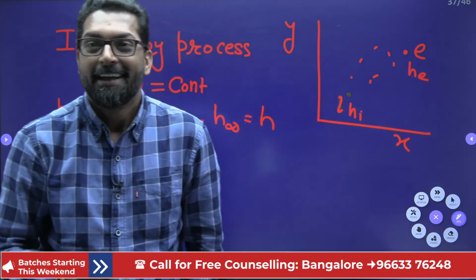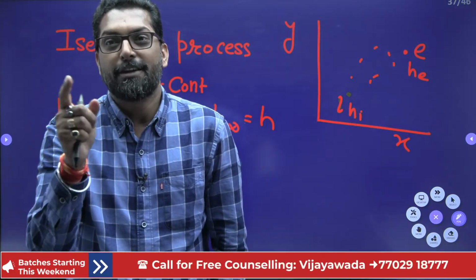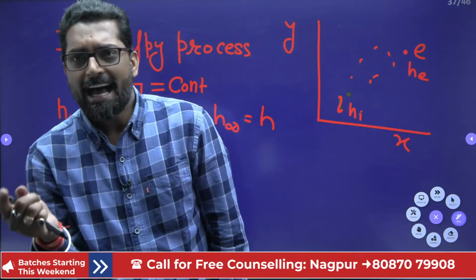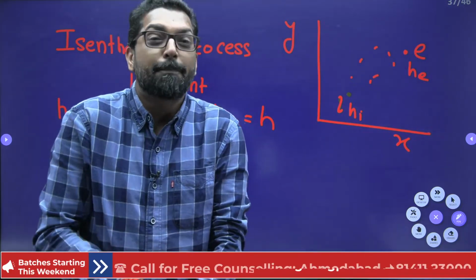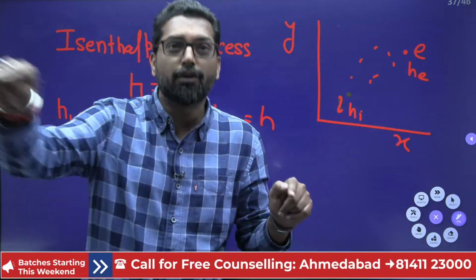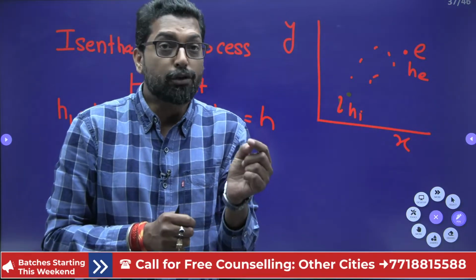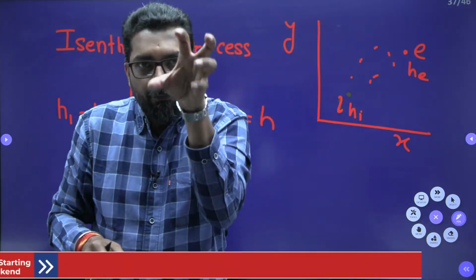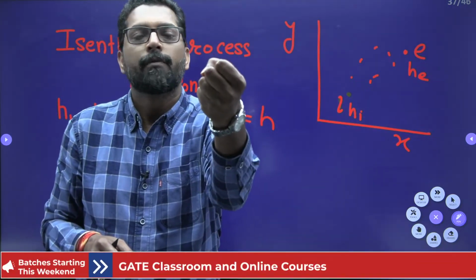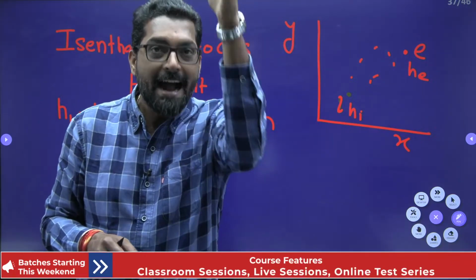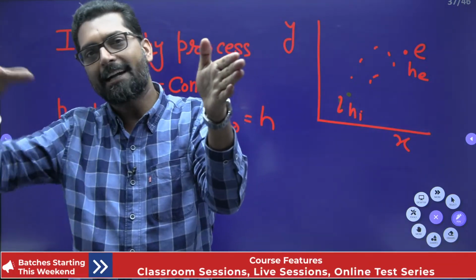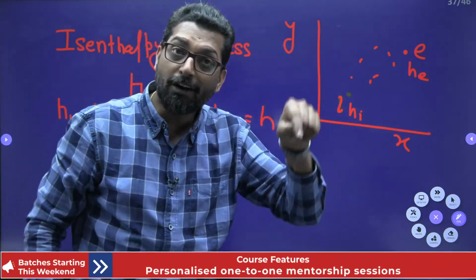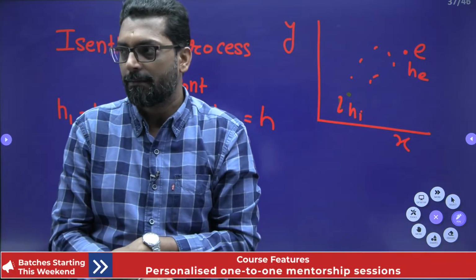That's why we will discuss whether the outlet product stream is more heated or cooled in the throttling. It will heat or cool, but enthalpy remains the same at inlet or exit, not during the process. During the throttling, enthalpy is not the same. But yes, if you take a fluid and measure the enthalpy at inlet, and then take that fluid at exit and measure the enthalpy, both are the same. But it is not necessary that during that process the enthalpy is the same.